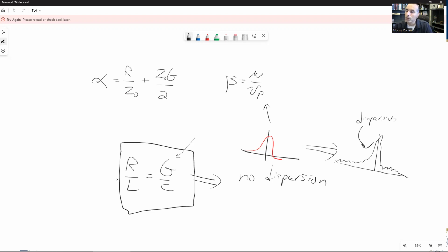The downside is you'll create a little bit extra attenuation, and so you'll kill your signal strength a little bit slowly as a function of length. But the flip side is you may be able to decrease your dispersion, and that is very important. If we're sending a digital pulse, for example, going back to the digital case, this digital pulse consists of lots of frequencies on up to maybe gigahertz. If this is a pulse with a rise time of a few nanoseconds, we've got gigahertz in this signal. You can't generate this sharp rise without a gigahertz component.